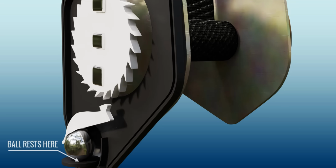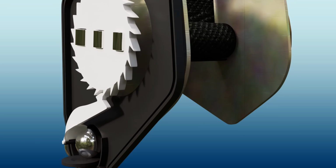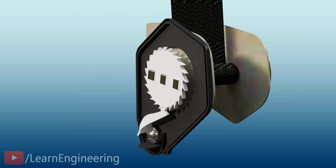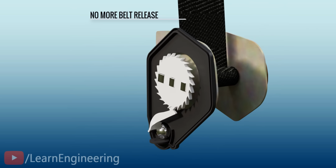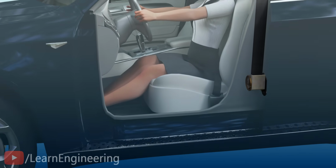However, when the vehicle stops suddenly, the ball moves forward due to its inertia. This movement will move the hinge and trigger a locking mechanism. This locking will prevent any further release of the webbing from the retractor, which means the seatbelt simply arrests your motion during a crash.